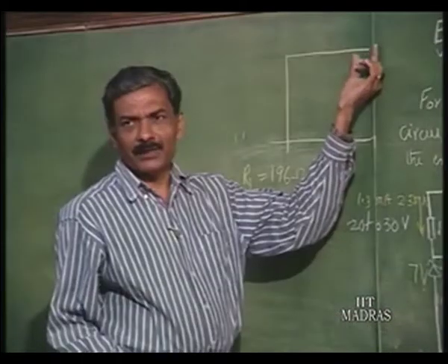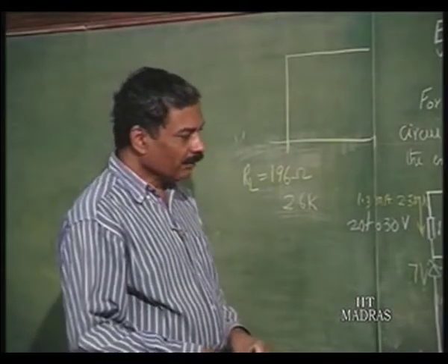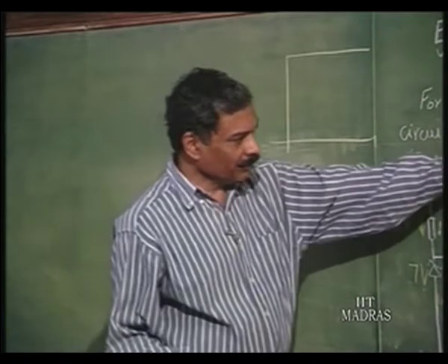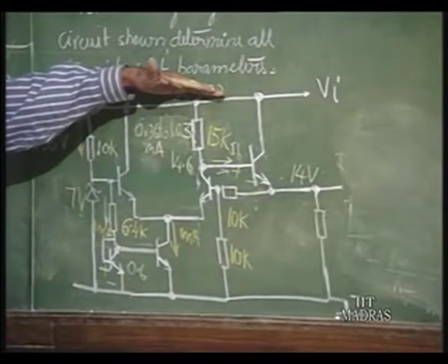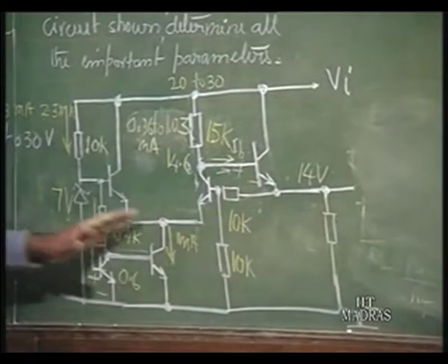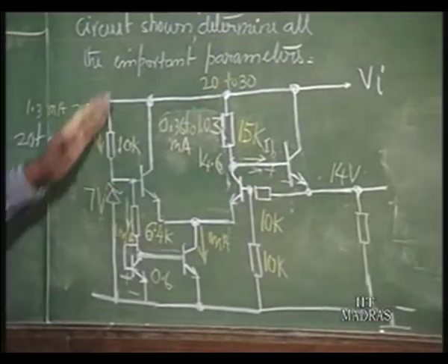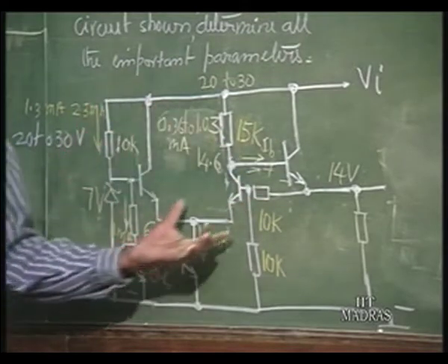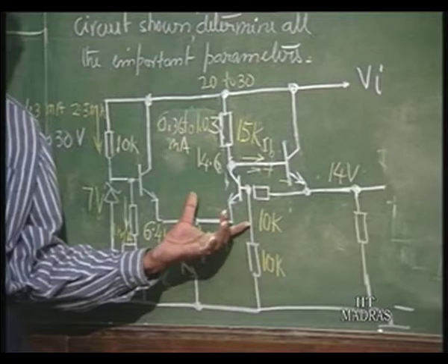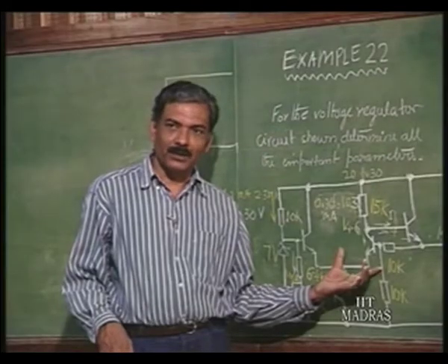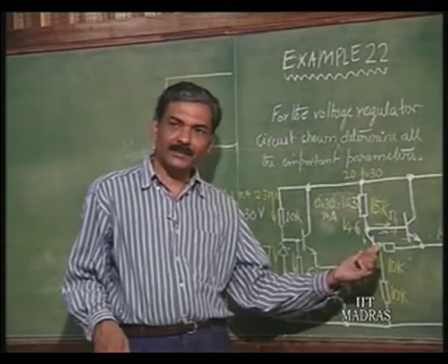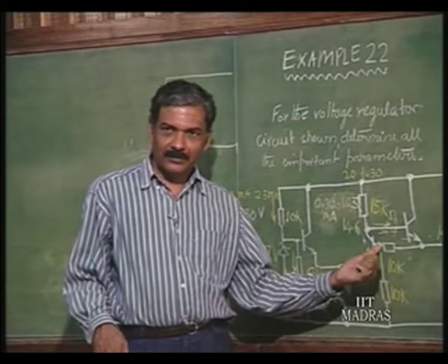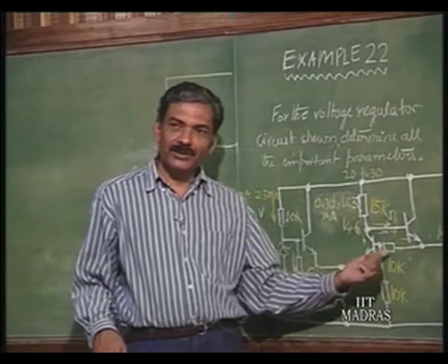This may be very small variation that is going to occur primarily once again as the input voltage is kept constant, okay, this variation is going to be occurring because of the non-idealities of this differential amplifier that we have, that is going to be extremely small. That is, we are assuming that the voltage difference is 0, it is not strictly 0, right. So, the error voltage is 0 is what is assumed.